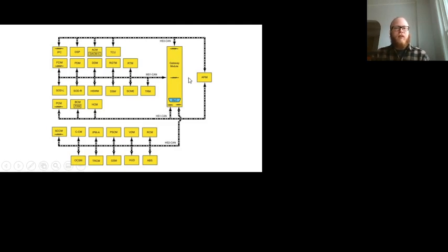And right off the bat, you can see that now my data link connector is part of the 31st module. This is its own module all by itself. We're limited in this case. Each network can hold around a maximum of 12 modules. They try to keep it just under 12 if possible, but if we start to get too many modules on this network, the constant chatter becomes too much, and it's just like being in a room full of people all having different conversations.